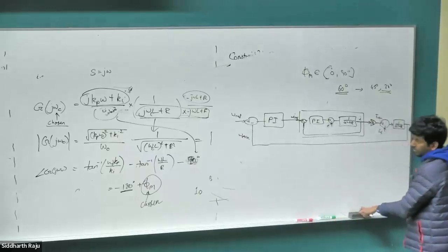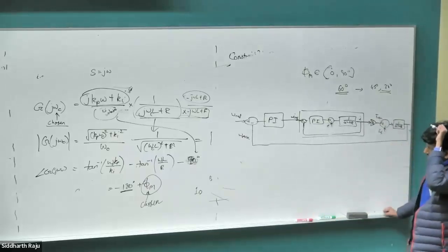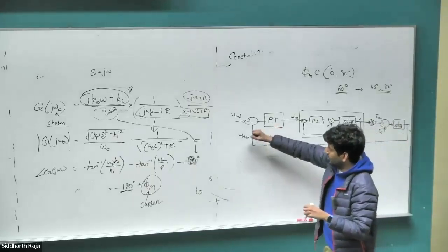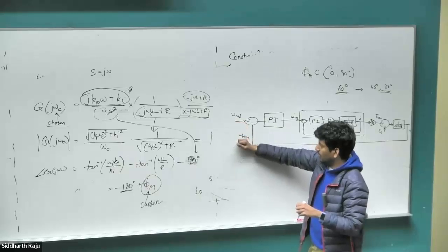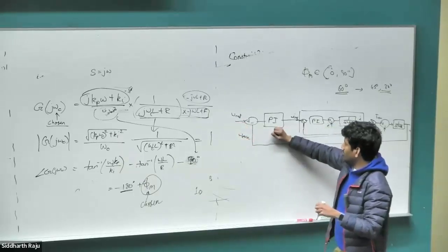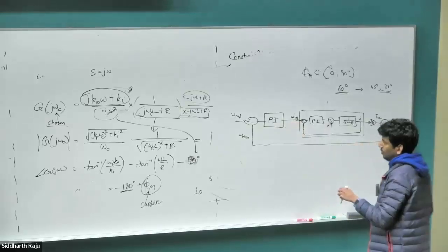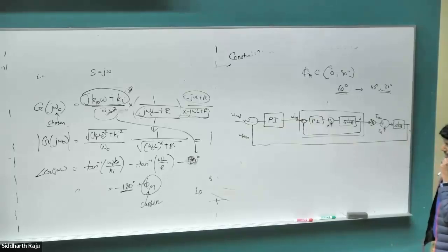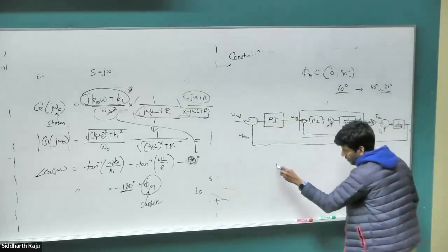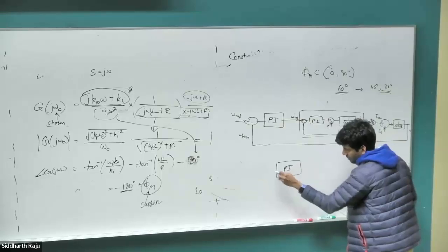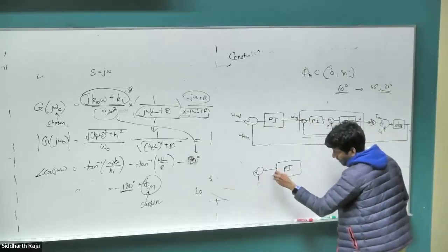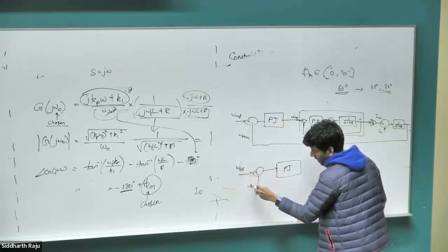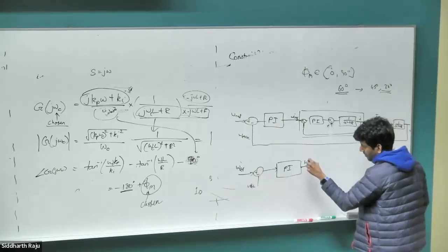Any other questions? Okay. So we are going to put another PI controller at the output coming from our desired speed reference. We look at the actual speed, put it to the PI controller, and connect it to our already designed control system, which requires some current reference to go into this. So this is one way of doing it, or the alternative was the first method that I showed, which was to take a PI controller, and then we have our omega reference, omega FPK.